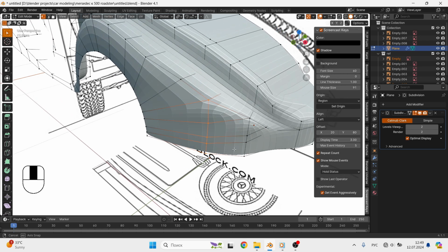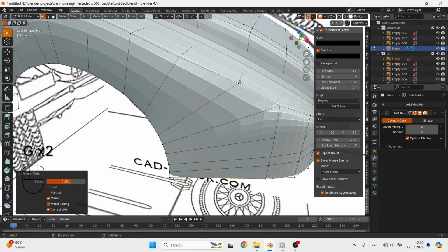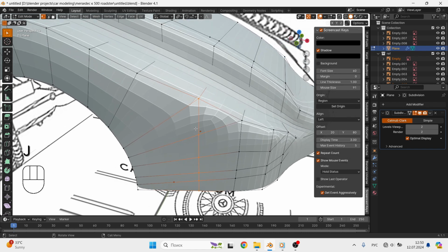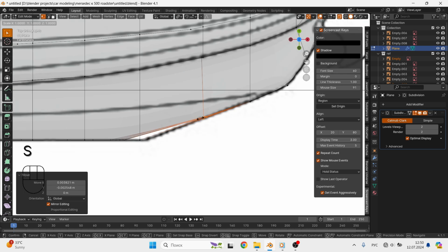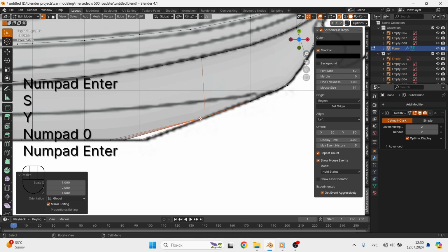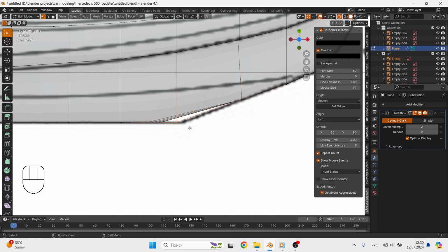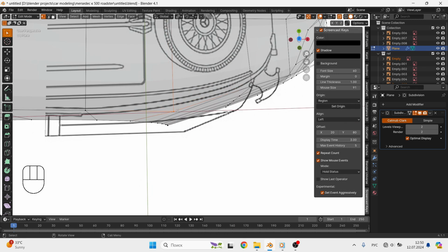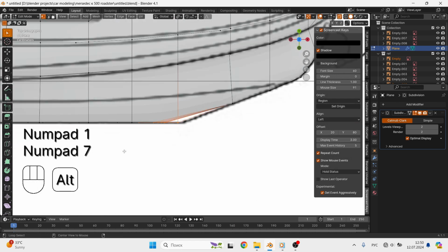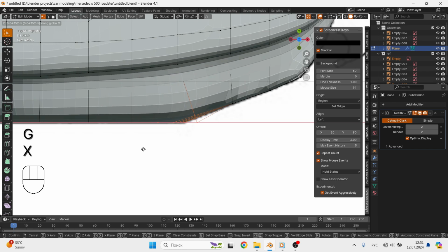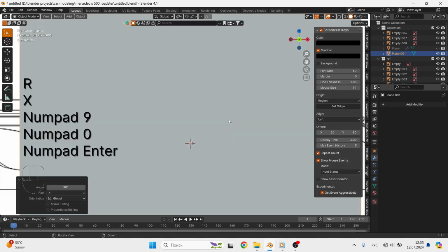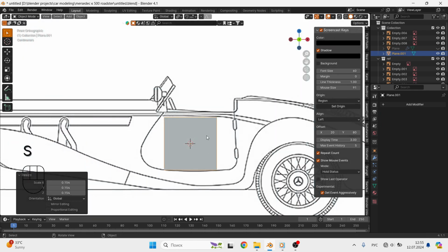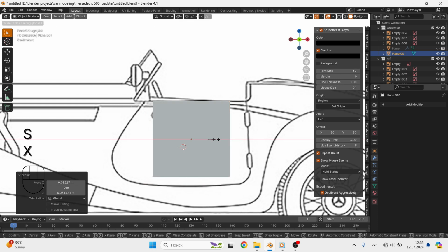If you look at it from a very professional point of view, Blender is not suitable for modeling cars. For example, imagine your UV sphere. It consists of polygons. And no matter how many times you subdivide it, it will not become round, the polygons will just become very small and invisible to the eye. Another thing you know in Blender is smooth shading, but the problem is smooth shading doesn't work in the real world, it's fake. So this also won't work if you actually want to produce what you designed. So that's the main issue in Blender.